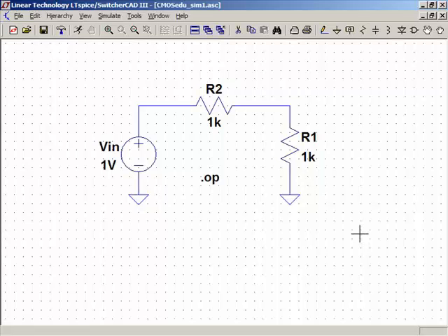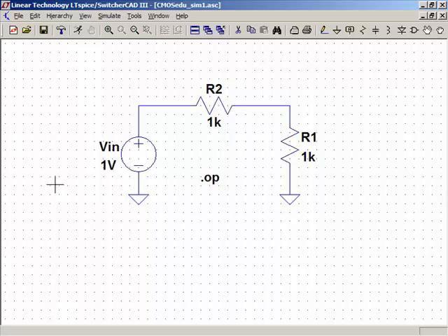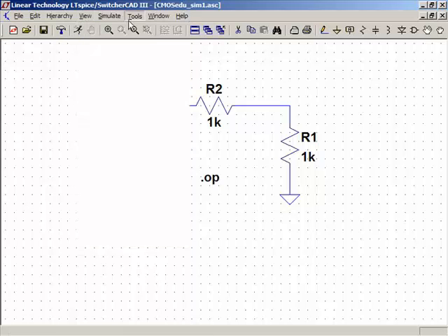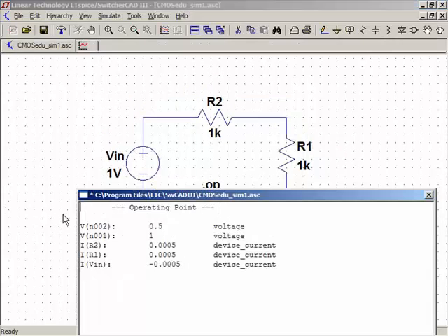Now if you ever write, of course LTspice will simulate netlists that you write by hand as well. And if you have a netlist where you've put O instead of 0 for ground, it could cause you pain. Okay, so we're going to run the simulation, and then what we're going to see is if there's any errors or anything like that. So let's hit run.